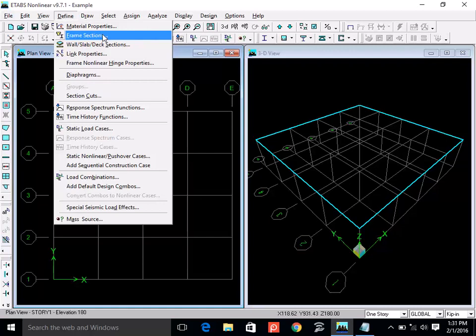And this includes the depth of the slab. When I say a 24 inch deep beam, it doesn't mean that the drop of the beam is 24 inch. It means that the drop of the beam plus the slab thickness is 24 inches, so from the top of the slab to the soffit of the beam is the total depth.